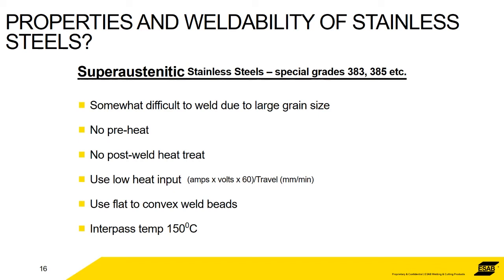So the attention to detail in terms of preheat and post-weld heat treatment and using low heat input has to be absolute. Okay, the design of the weld bead, flat to convex.